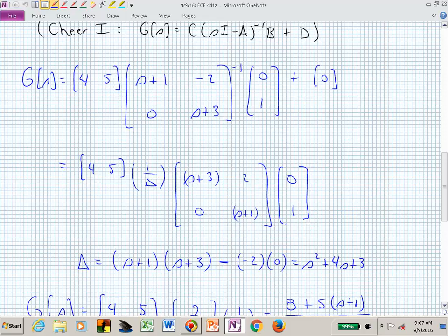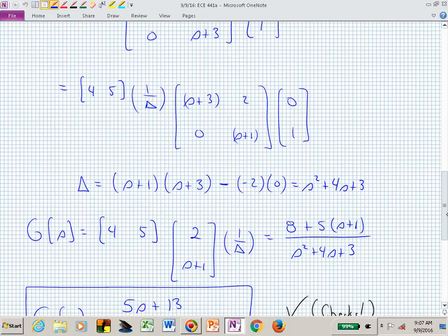Is the system stable open loop? Yes, because we have negative real parts on those eigenvalues, or on those poles. And in this class, what we will be worried about is if our system is not stable, or if we don't like where those poles are, we want to be able to change those pole locations with feedback. Here, we are just looking at the open loop behavior or dynamics.